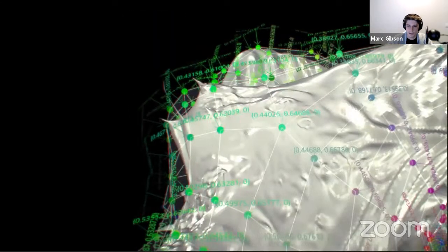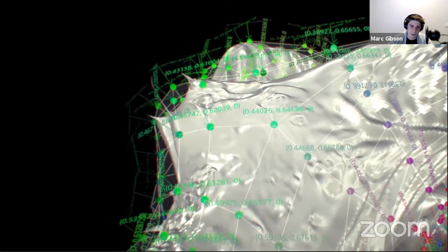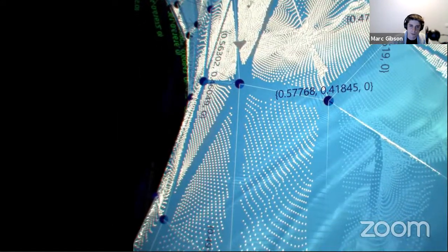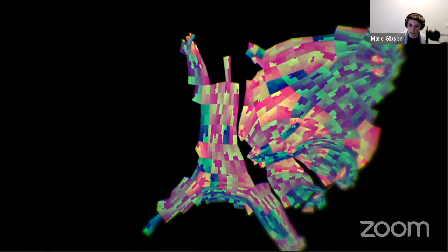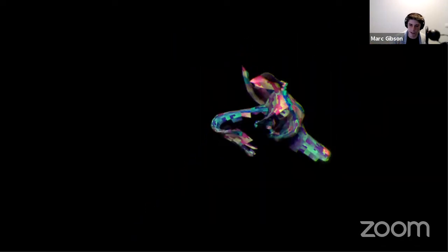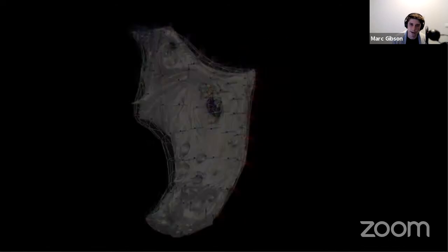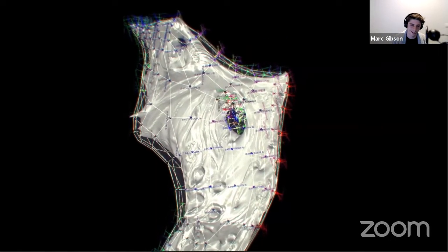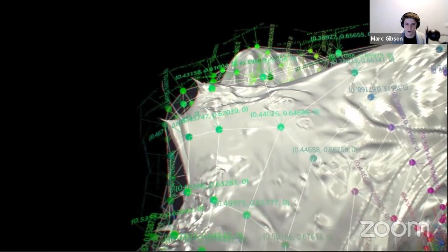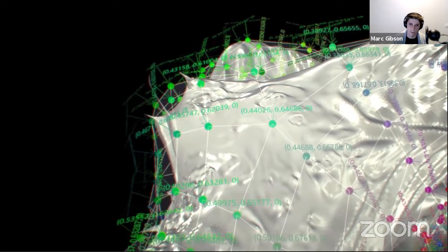And this is done by essentially interpolating the texture coordinates of the face and the relative position from the corners of those vertices. And so this is done at the initial stage. And so once the object has inherited those qualities, as the mesh subdivides, it would then just interpolate the texture coordinate from there. So as it grows, you don't have to recalculate or re-pull the UV coordinates from this.